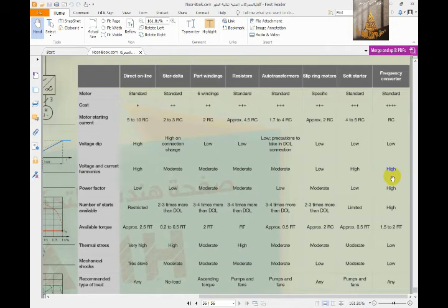So the soft starter and frequency converter also have filters to drop these harmonics. The filter may be contained internally in the soft starter, or in the frequency converter, which I'm sure has filters internally.